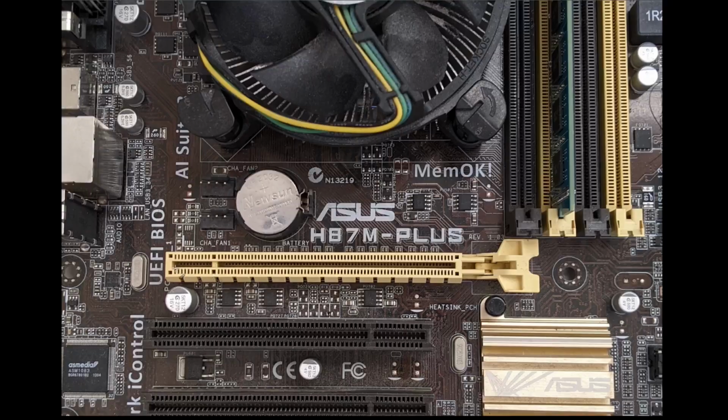The top port of this board is a PCIe X16 lane, but what does X16 actually mean? In the concept of PCIe, a single lane is a set of differential signaling pairs, one for the transmit side and one for the receive. In this particular model, we have PCIe generation 3, so a single lane with these 4 wires in total, 2 for each side, can do about 985 megabytes of data per second in a single X1 lane.